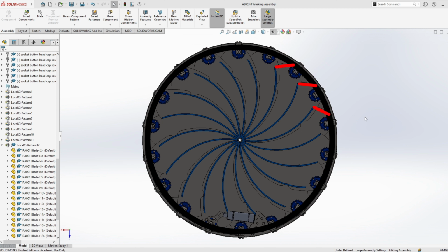So an important feature of this design is each of the blades have a main pivoting point on the body enclosure of the system for this mechanism to work. So I'm just going to draw this pivoting point. Say about here, here and here. So when the big black ring rotates now, the blades all turn on the hinging points as the red control arms push or pull the blades, opening and closing the aperture or the diaphragm.